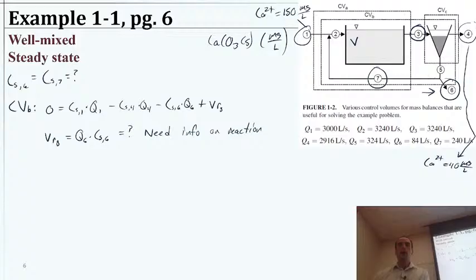Okay, so I thought to myself, well, let me see how far I can get with the solution for the concentration of solids. I'm writing this as C_S,6, which would equal C_S,7. And so I took control volume B that's spanning the whole thing. When I set up a mass balance there, took it at steady state, so 0 is the net accumulation. We had our inputs and 2 outputs.